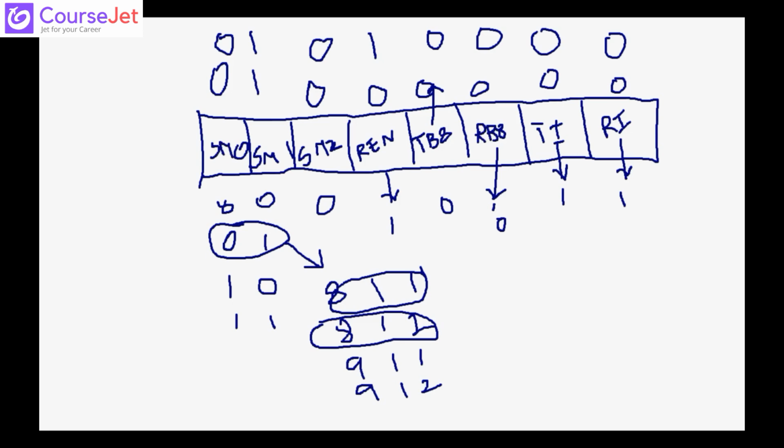the timer 1 register in mode 2. Then we need to select the operation, whether you want to receive or transmit. Generally, we always write this value as 0x50, because you are not going to do only the transmission operation, you are also going to do the receiving operation. So we just enable the receiving option also, and we load SCON equal to 0x50.